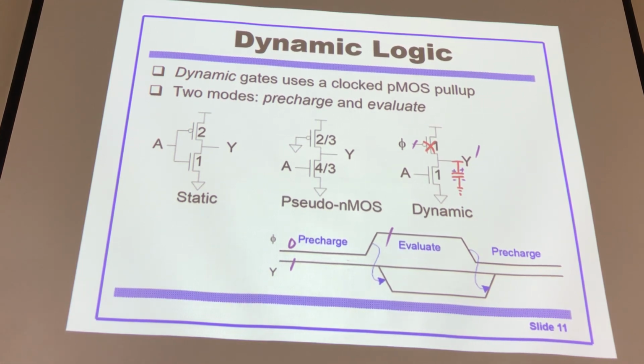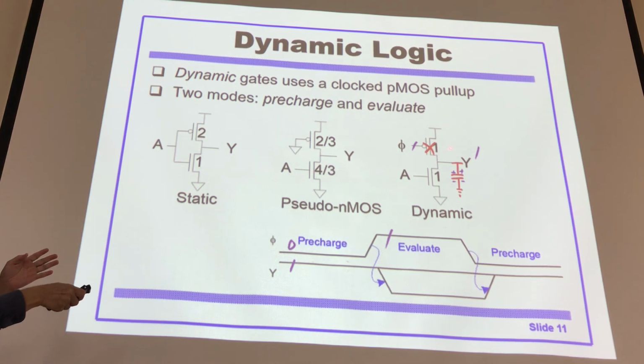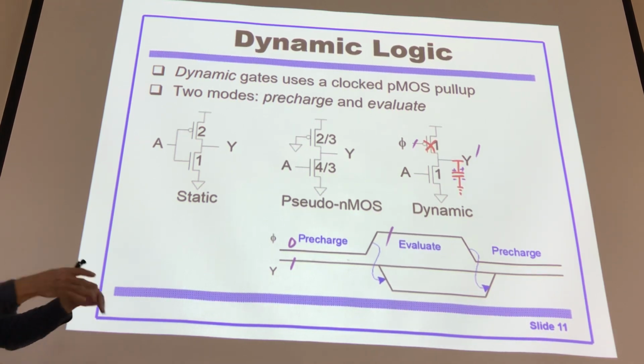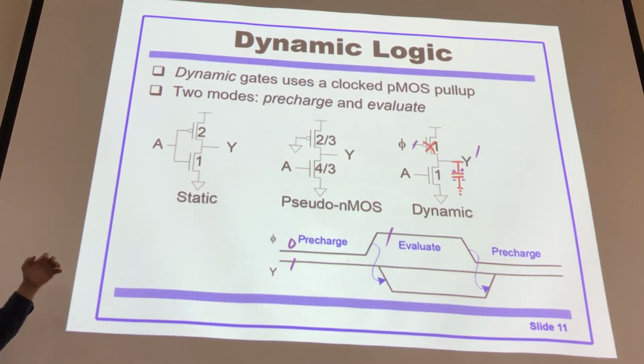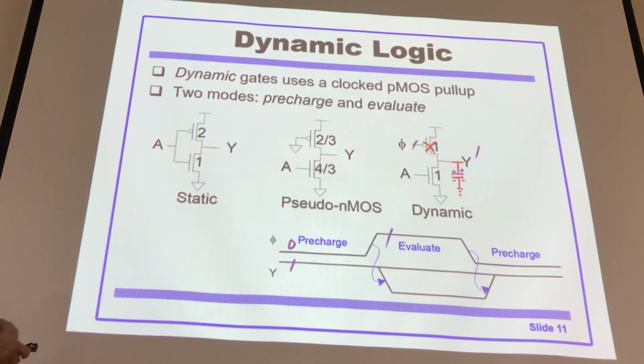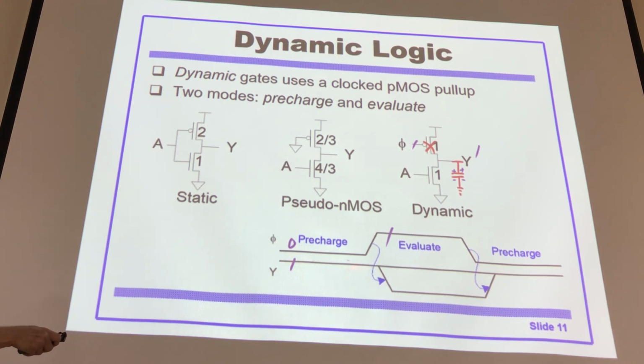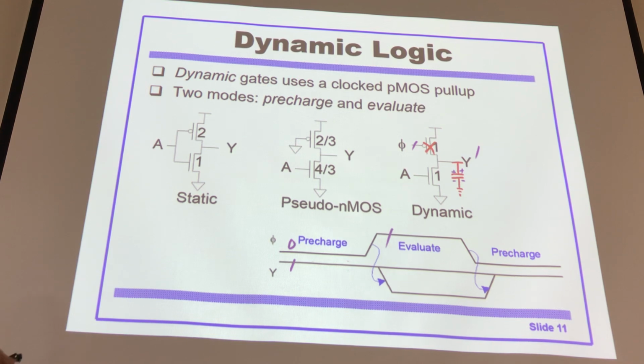Okay, let me repeat it. Clock signal is 0. PMOS is on. So there is a current from VDD toward the ground going through the capacitor. So you try to charge the capacitor, try to accumulate more and more positive and negative charge on the capacitor until it reaches signal 1 for voltage. It will have enough time to charge it.